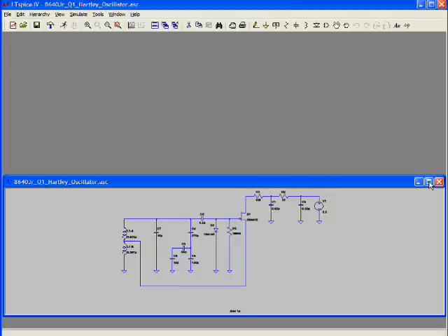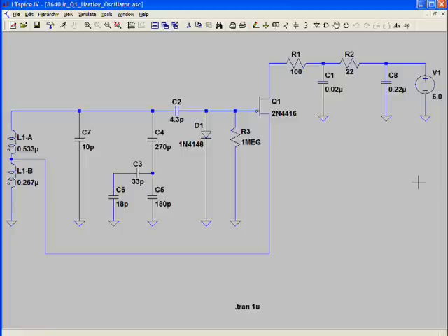in Spice, or in the real world I should say, when you start up a circuit, there's natural noise in the world basically, that will be induced on various components, and thermal noise, things like that, and the voltage starting up and going from 0 volts up to the supply voltage will kind of kickstart the oscillators and stuff. But in Spice we don't have that unless we tell it to do it.